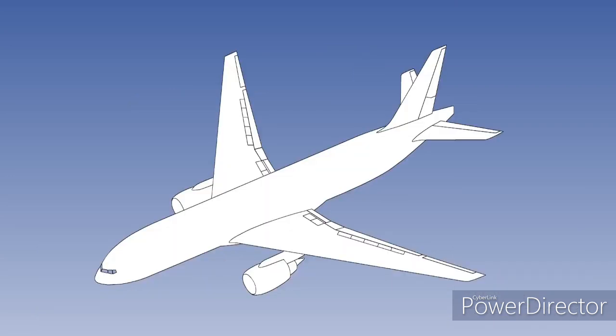You have been shown that large and/or fast aircraft have high stick forces because of the large hinge moments generated. Stick forces that are too high make an aircraft difficult for the pilot to control. If aerodynamic balance cannot provide the required assistance to the pilot, powered flying controls must be used.